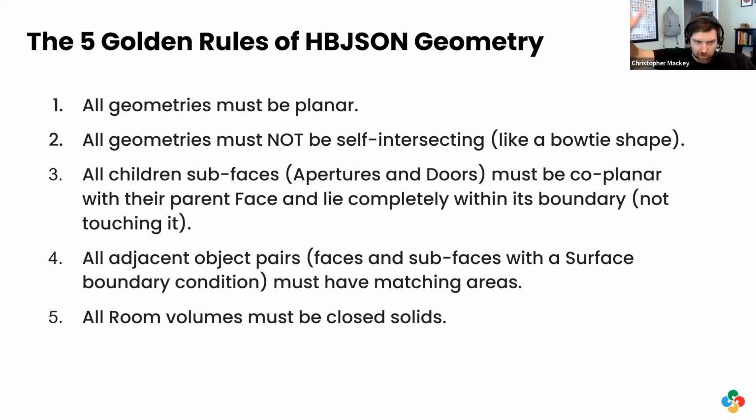So you just follow these 5 geometry rules. As long as you make sure that your input geometry is following these 5 rules, all the other idiosyncrasies of different building energy modeling platforms you don't have to worry about. You don't have to worry about counterclockwise vertices or the native tolerance of EnergyPlus. All that we just take care of for you in your translators.